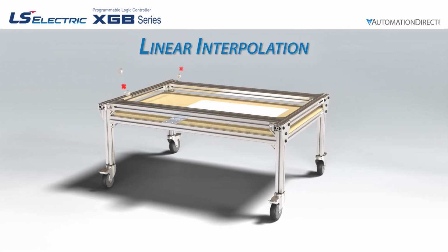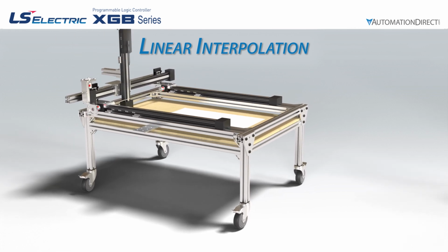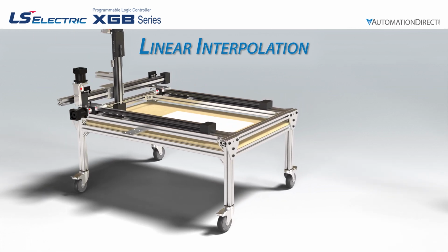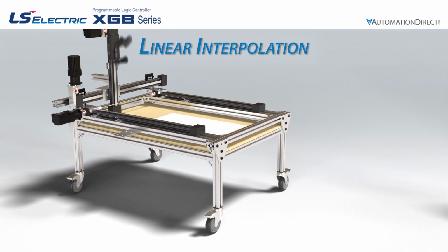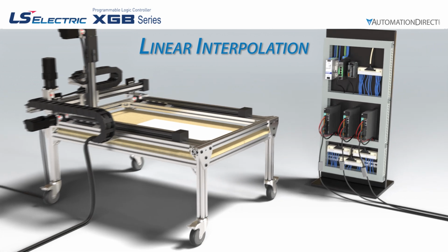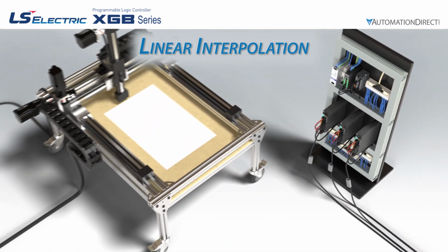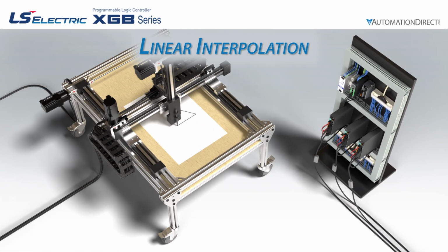It utilizes IGUS drylin actuators and Sure-Motion couplers from AutomationDirect attached to LS Electric gearboxes driven by L7P servo drives and motors. These drives are controlled by pulse train outputs from an XEM-DN32HP 6-axis motion controller. We have attached a mounting plate and pen to allow us to trace the profile we will be working on today.